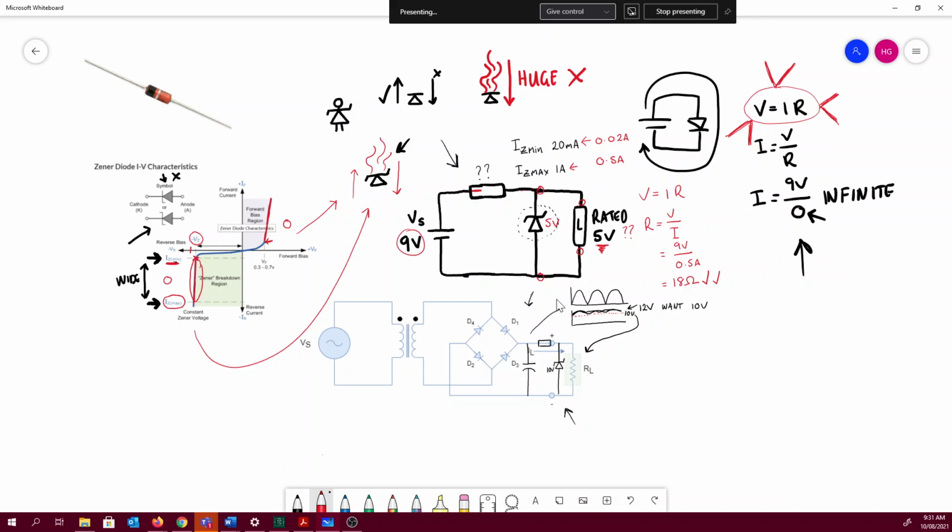That would make that work just fine, because what you'd find is that you'd have about half an amp of current through this Zener diode. And from these numbers here, we know that that's nicely somewhere in the middle of its range, happy to conduct without being too limited or getting too hot and having the magic smoke come out. And so that's how that works, right?